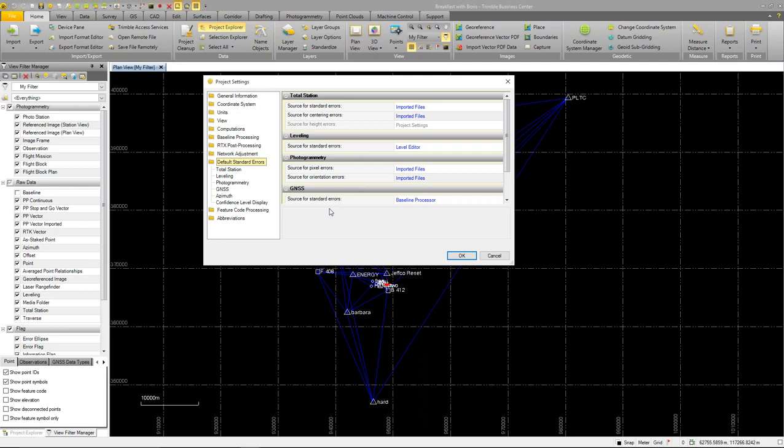And that set of parameters is different in its general nature from the site calibration parameters you get in using RTK, because the site calibration parameters are more where you're matching a set of coordinates by rotating, scaling, and translating them to another set of coordinates.